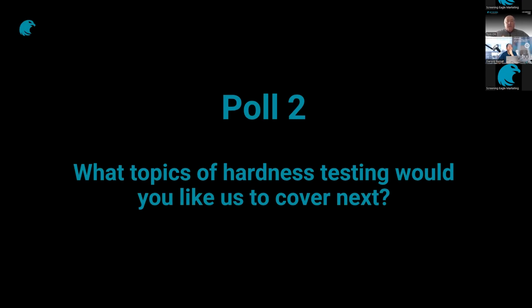The first way to do it, prior to doing any testing with the Equotip 550, is a surface roughness comparator plate that we came up with. It's a little plate that fits in your pocket that has the various minimum surface roughnesses on the surface.